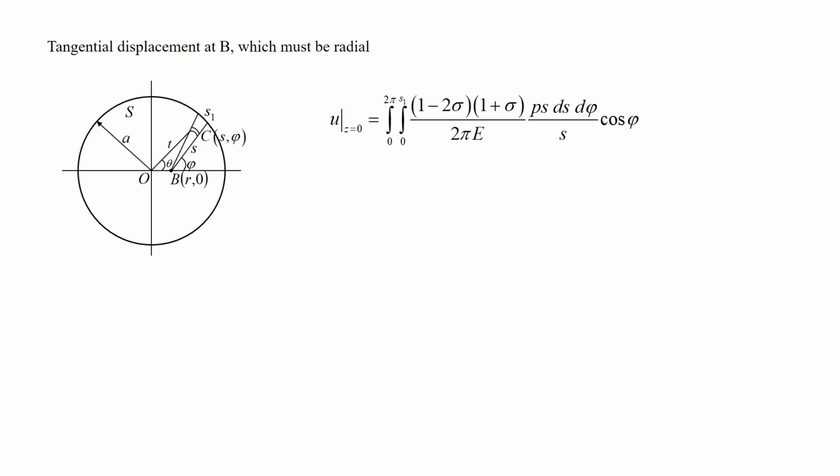Now, what about the horizontal displacement? Remember I had discussed this also in the last class. Here, for example, the load is being applied over here. The horizontal displacement for this particular point because of this load will be along this direction, because the vertical load, the pressure, is being applied on this point.